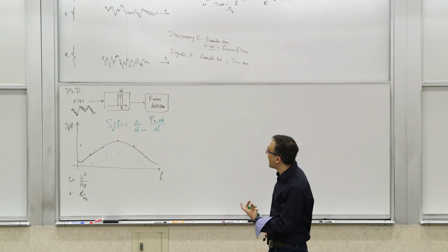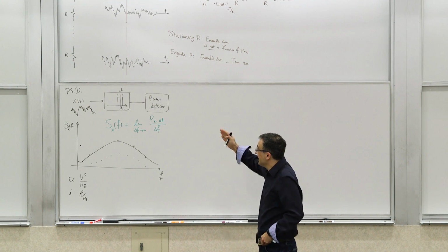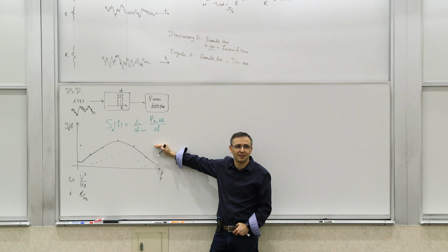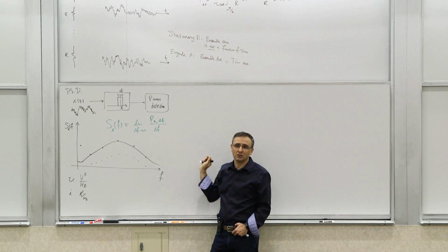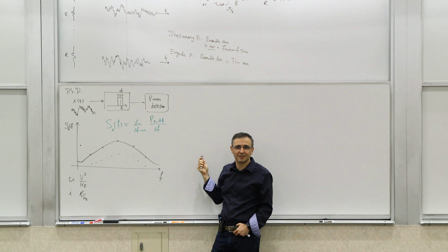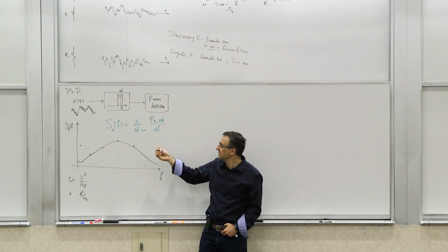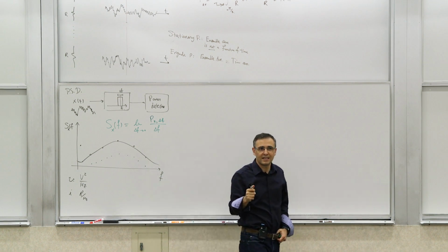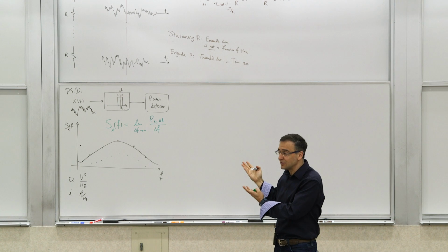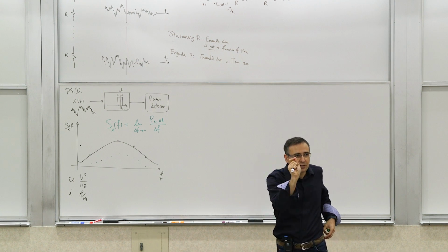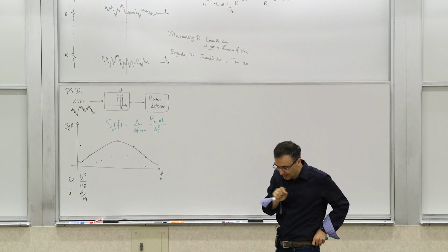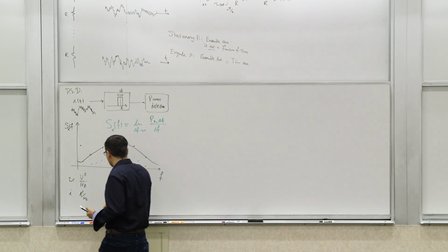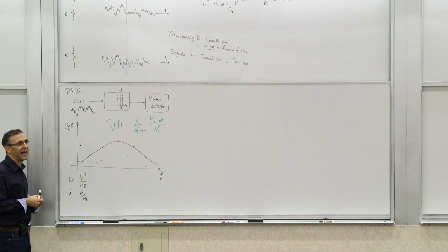So this power spectral density, and let me emphasize this, this is the definition of power spectral density. The relationship with autocorrelation, which we'll talk about in a minute, can be directly derived from this definition. So that's not the definition; this is the definition. This makes sense, right? You measure the power in every single bit of spectrum, every bit of the frequency. Now, you can get all sorts of different kinds of spectra, and we'll talk about them and what happens to them.